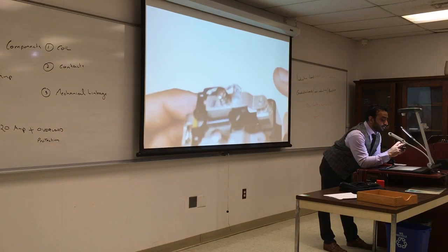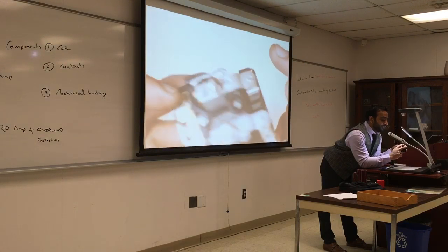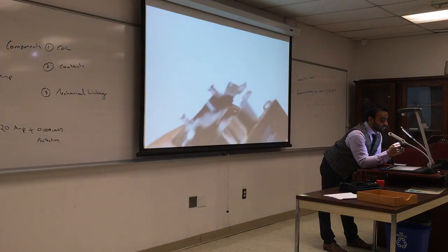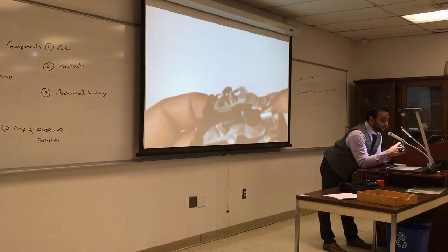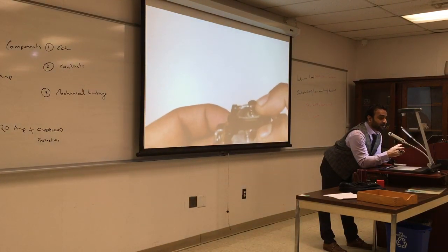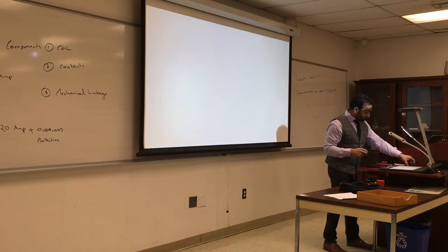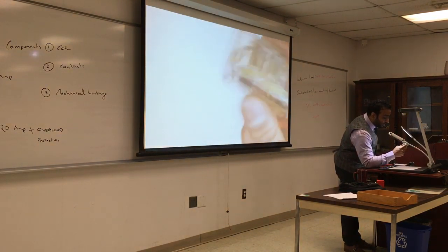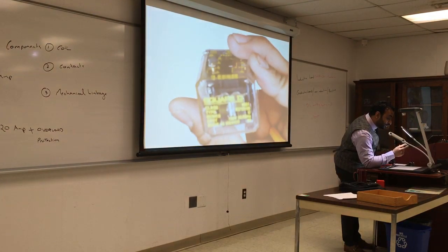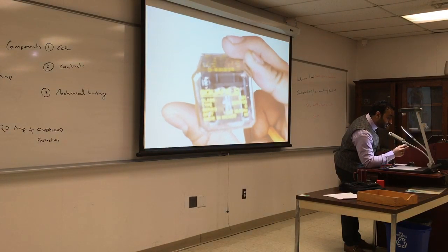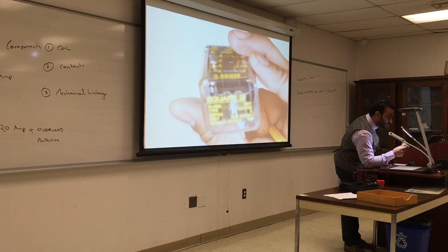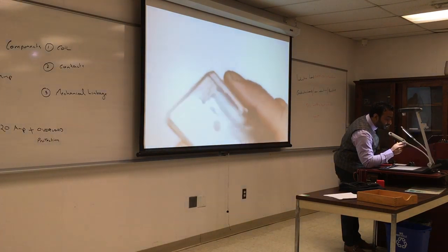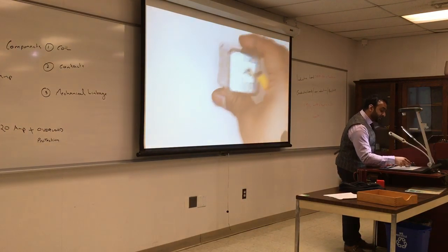And the springs are to give it some kind of push and pressure. And these are the terminals that will be connected. So this is going to go to the AC, and this is 220 volts, and this will be 24 volts here, and we'll just connect them together. This is another small relay, and this is 24 volts. Actually, hold on. The coil here is, come on, tell me. It's 120 volt coil.